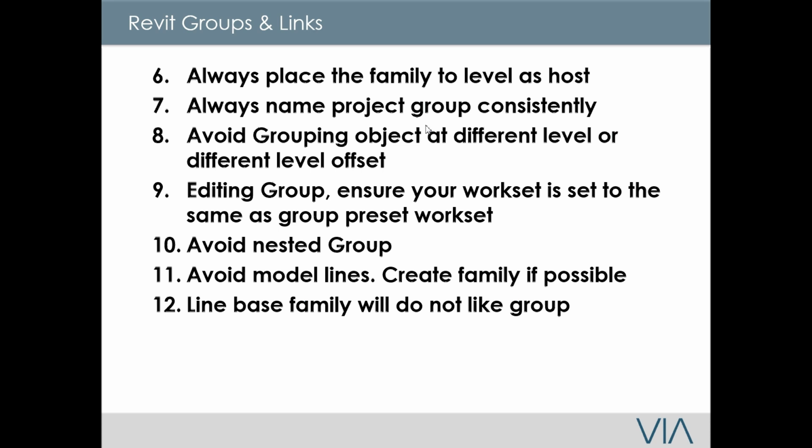The minute that you have placed the group in the wrong work set, what tends to happen is that it will start to show up when you start to print. So it's a good idea that you make sure if the group is furniture work set, you change your work set to furniture and add your furniture. Okay, just the pet peeves. I mean, sometimes people avoid doing this. That's fine. And then this is where the BIM manager has to come in and help clean this up.